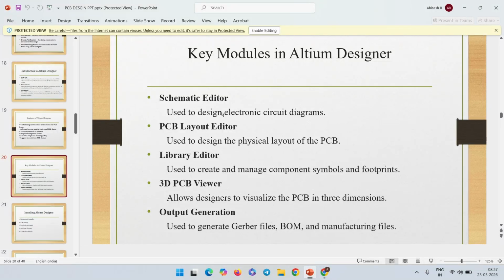The schematic editor is for editing a schematic, like a circuit connection diagram. In the schematic editor, we can place components and connect one component to another. If you have to edit a connection, you can clear the previous connection and draw a new one. Also, you can see some components placed at the top of the schematic design sheet, mainly for placing new components like ground, no connection pins, and other things.